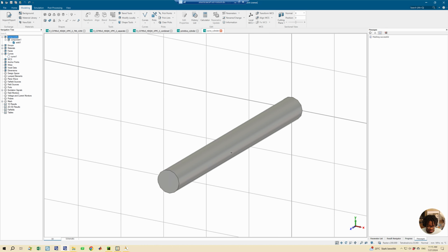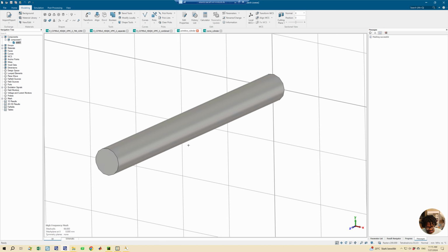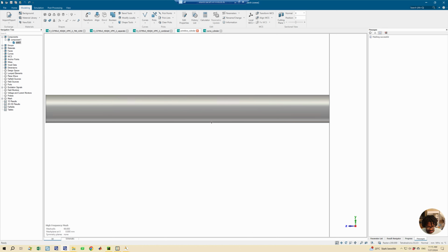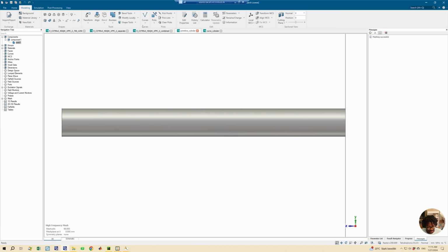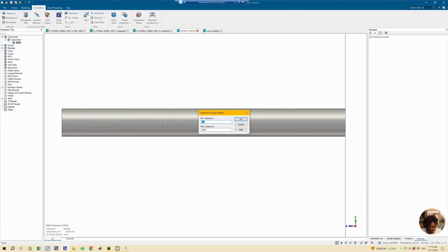So graphically they look exactly the same. They look exactly the same from all sides. I mean, it's the same dimension, so it should look the same. However, let's see if the mesh generated is different. Now, I already went ahead and generated the mesh. Now, one thing we notice for the tetrahedral mesh and my settings, so the frequency, I just set a random frequency, max frequency of 1,000, and all other settings remain the same. So the only thing that is different with these two models, this and this, is the way they were modeled. So the same cylinder, the same dimension, but a different process.